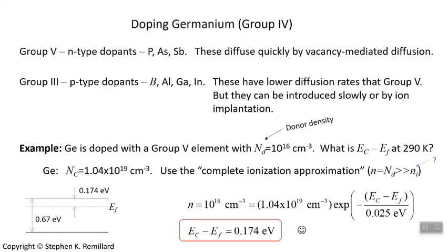It's always below. If the Fermi energy is above it, what's called a degenerate semiconductor, it is possible to send that Fermi energy into the conduction band, at which point the semiconductor starts to behave like a metal. Okay, there's an example. We just calculated the new Fermi energy location based on doping density in germanium.